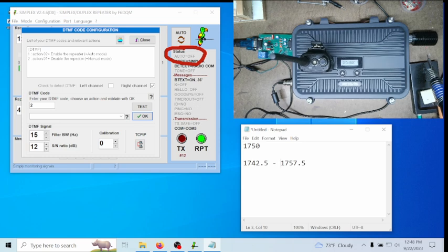The signal to noise ratio, SN ratio, is the sensitivity of the tone detection. So I know what you're thinking. Well, I'll just turn that way down so that it's real sensitive. No, don't do that, because then it could pick up noise and trigger it, and it's going to be playing your functions randomly because it's picking up noise.